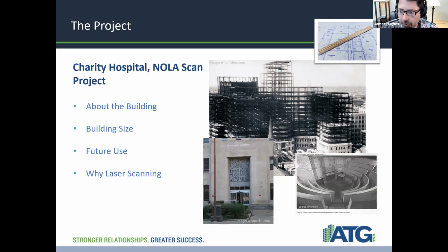Jeff, how good of a job do we do with measuring or laser scanning the plenum space? In the plenum space, what we generally have to do is we remove a couple of tiles and just scan in the room, and then in the ceiling space. It's going to depend on how crowded it is up there on the information that we're going to get. We could go up more than one time in an area if need be to get around mechanical stuff. But if it's wide open and you're trying to get structural, it's pretty simple, but it does double the work in the scanning process. Okay. So you can locate in that plenum space the structure.